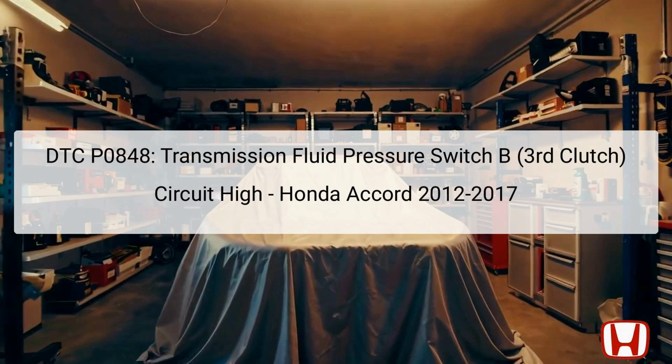The transmission fluid pressure switch B acts as a signal detector, determining whether hydraulic pressure is being properly applied to engage the clutch. If the switch fails, the vehicle's powertrain control module, or PCM, recognizes this anomaly based on the signal it receives. The PCM utilizes the signal to ensure smooth gear shifts and avoid transitions that may cause mechanical shocks. When the switch fails to operate correctly, a high signal is registered, leading the PCM to store this DTC.